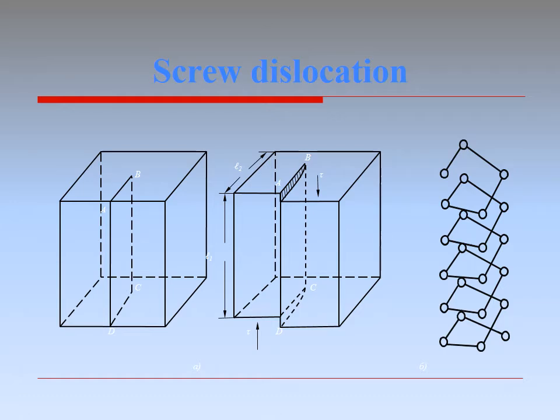Dislocation cannot end inside the crystal. Consequently, the dislocation line may close or terminate within the crystal on its surface. Some parts of dislocations have edge or screw character, but much of it is not parallel and not perpendicular to the shear vector. Such dislocation is called mixed.